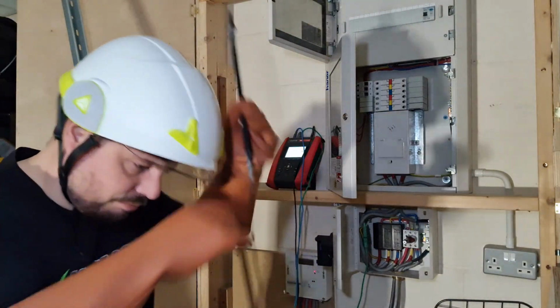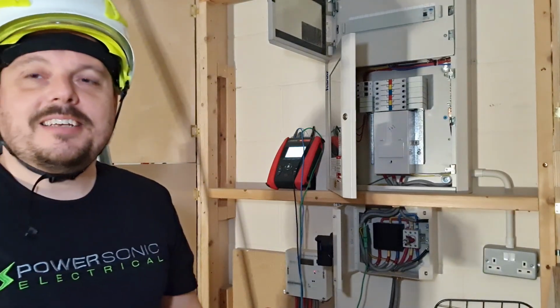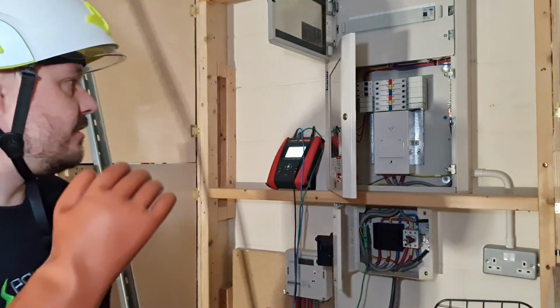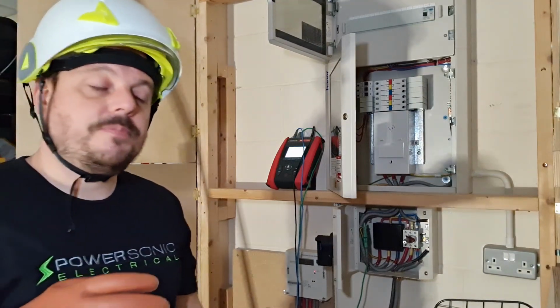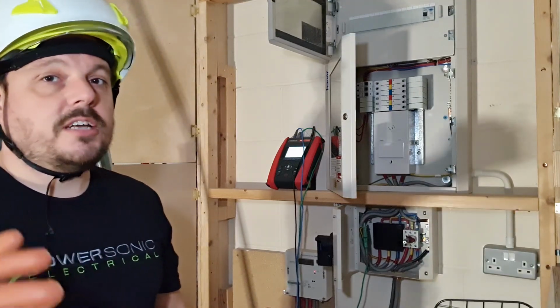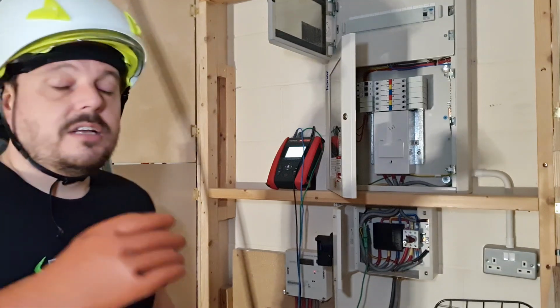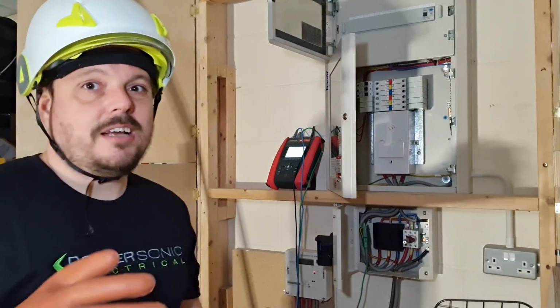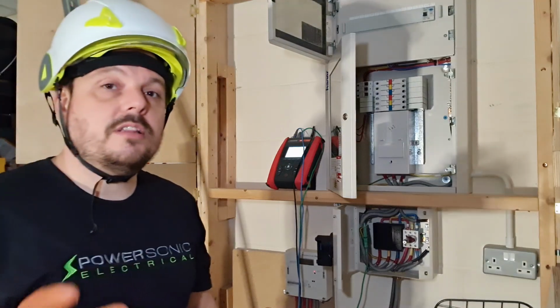Pop this up. So stepped away now, and yeah, it's coming out roughly 2 kA on your single phase prospective fault current. Obviously with it being 3-phase, there's some other calculation to look at with that, so we'll jump into a bit of information of that later on in the video. And 0.09 for the Ze, you know, which is quite a low value. I have measured lower than that here before,